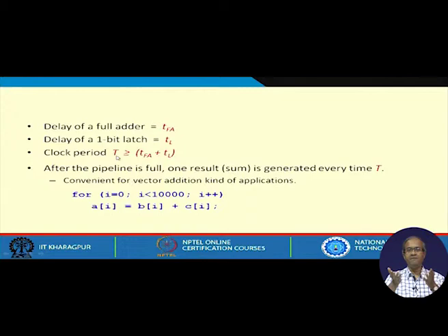Earlier, in a 4-bit adder, we were getting one result roughly every 4 times the delay of a full adder, but now in the pipeline implementation we will get one output every clock cycle. That is the advantage.